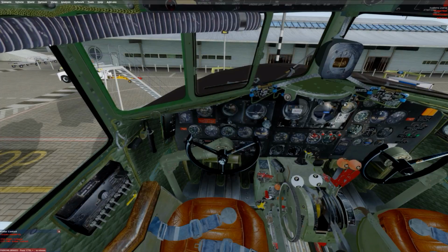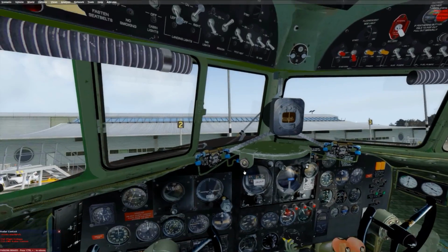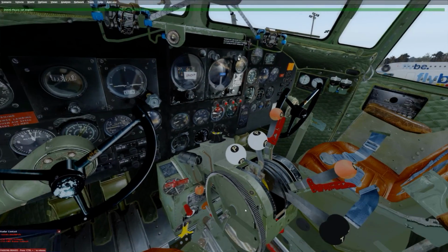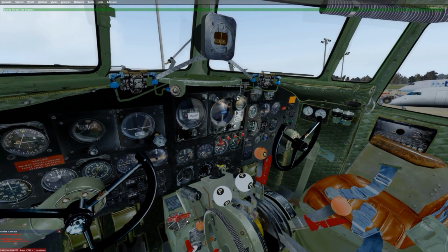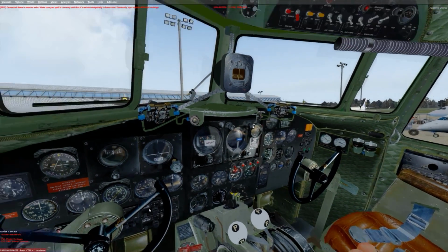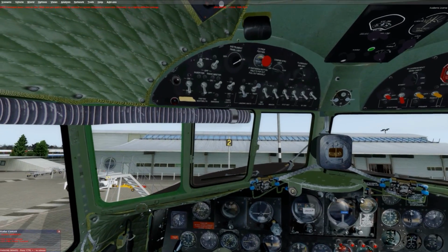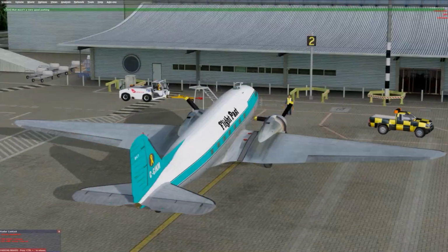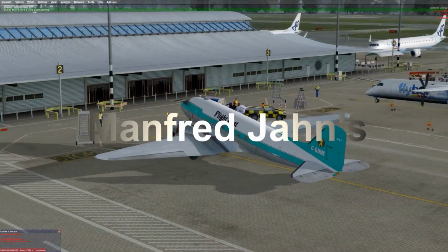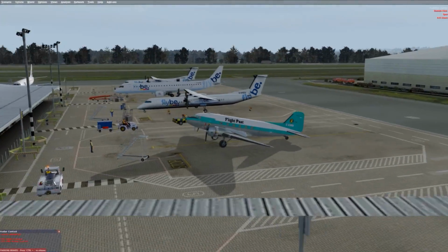Shutdown flow. Roger. Parking brake set. Engine anti-ice 1, 2, off. Navigation lights selected off. Seatbelt warning lights off as per instructions. Engine shutdown. 1. Closing down the engine. 2. Beacon lights turned off. We are all shut down, David. How about a drink? Shutdown flow complete.